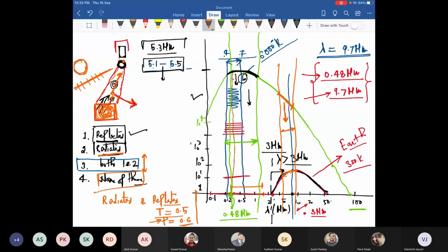In that case, you can say with surety that the sensor can get the reflected energy component, because 50% of energy is allowed by the atmosphere within this range. So it is 0.5, and 60% of the energy that is interacting with the earth material is reflected back. So obviously it will go to the sensor field of view. Is it correct?